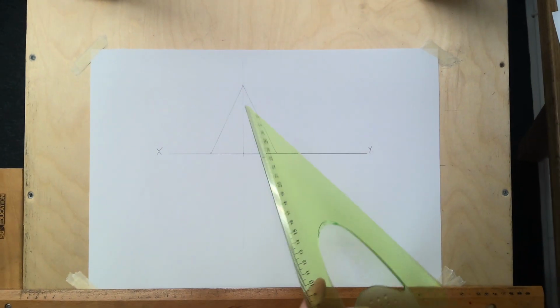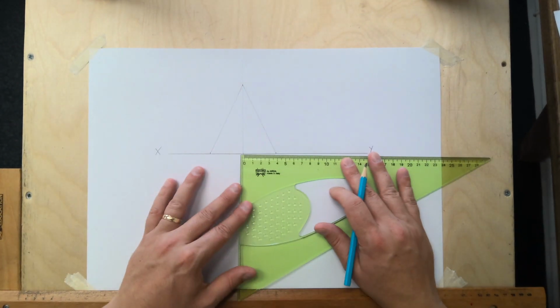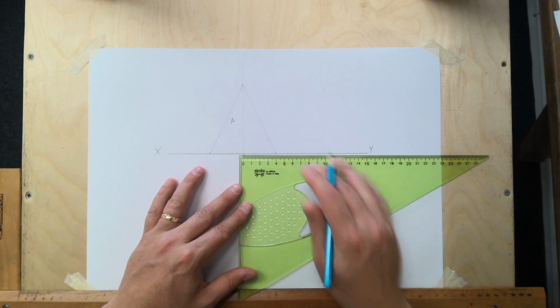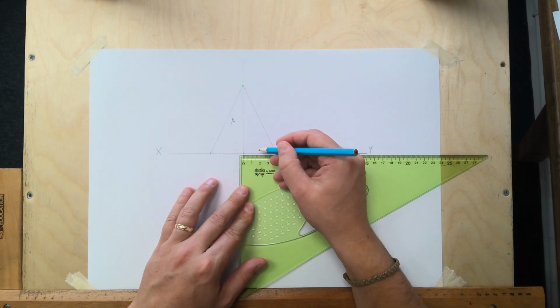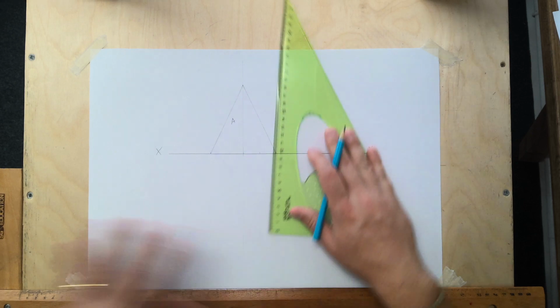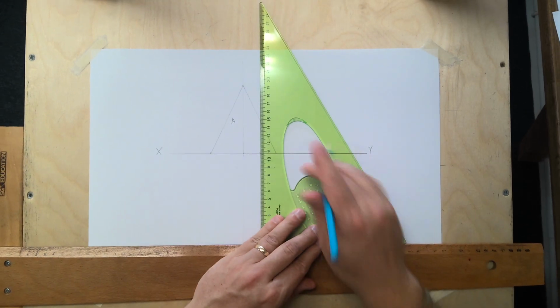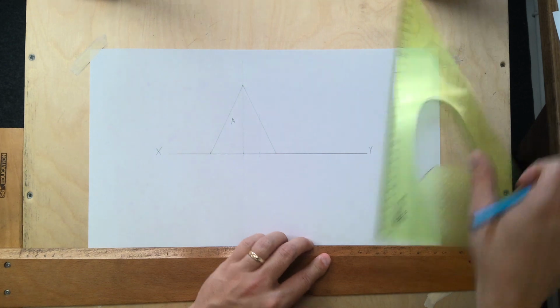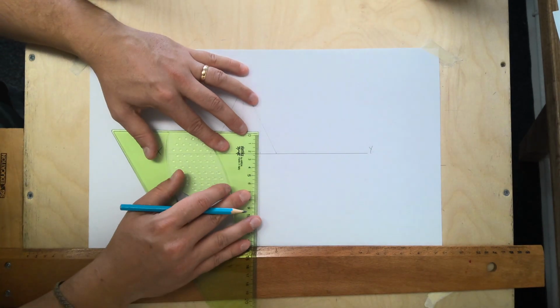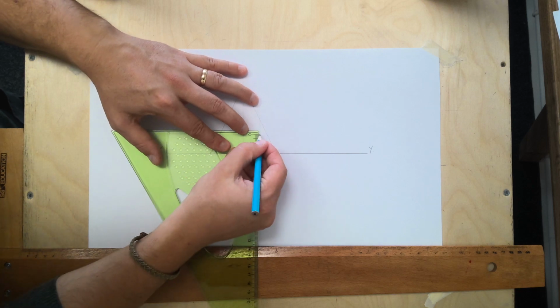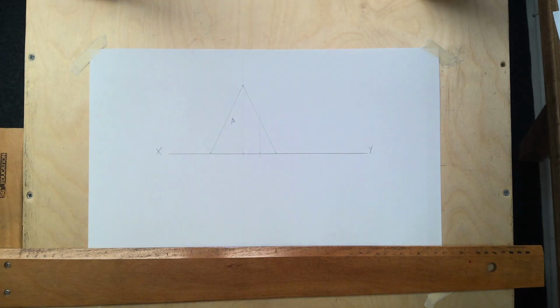Now that is A, as it tells us. Now we're going to pop in sphere B, it tells us it's 20 away here. But the center point is 20 away, and it is radius 24. So step up 24 off the ground because it's resting on the horizontal plane.